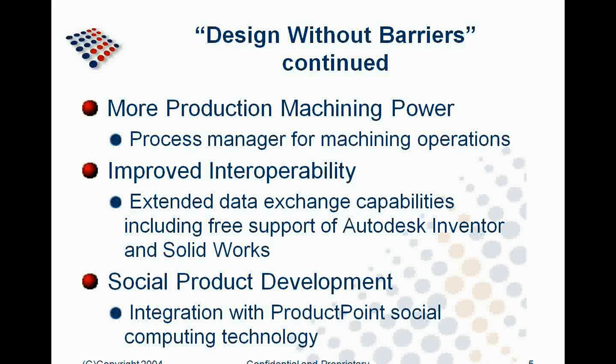In terms of machining, we've added in a new application there, so now that we can copy, save, and reuse tooling paths. So if you're doing the same type of roughing or finishing passes on a specific machining operation, you can save those parameters and reuse them in further operations.